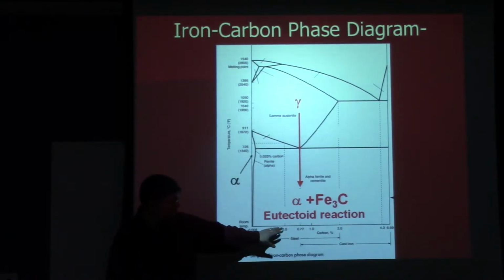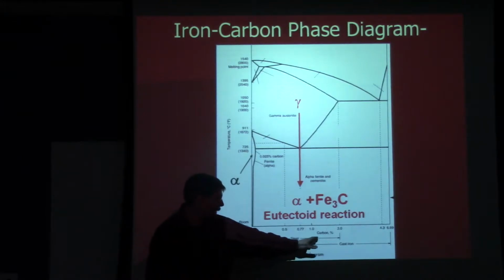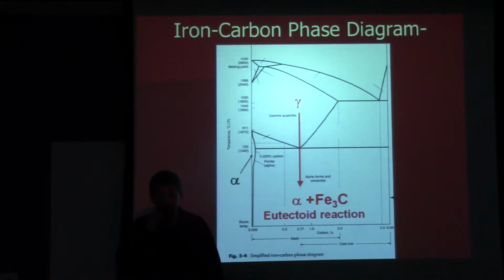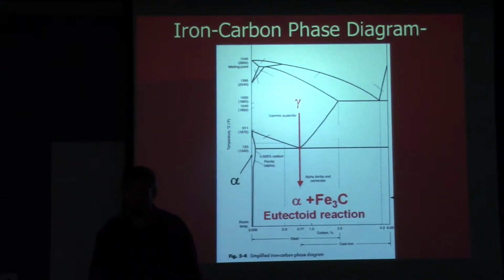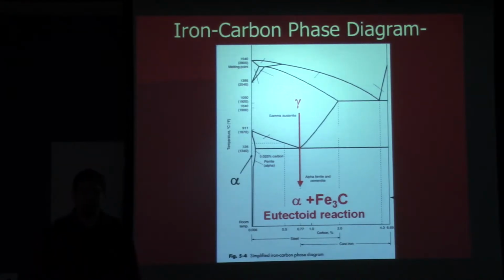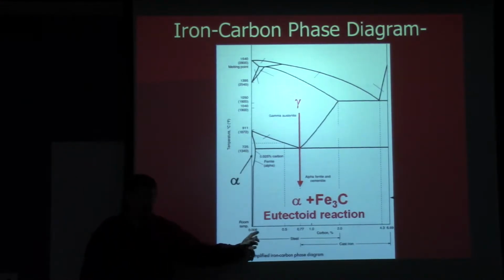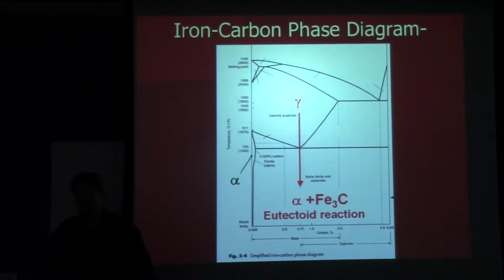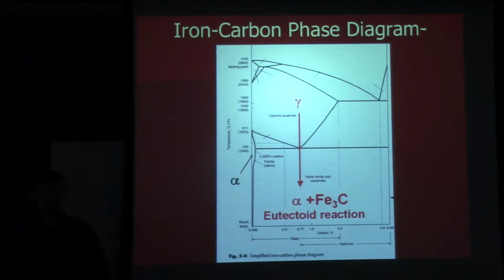There are exceptions, but in general, that's where they're at. On the cast iron side, I'm not sure where they typically fall in terms of carbon content. Well, I made a graphitic ductile iron that has 1% carbon. Okay, so you can kind of be in a lot of different places there depending on what you want to do, which is one of the nice things about metallurgy.